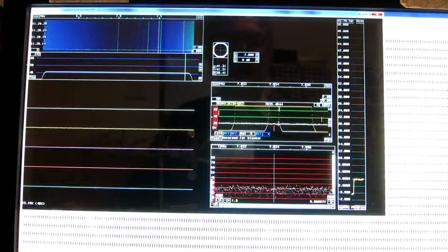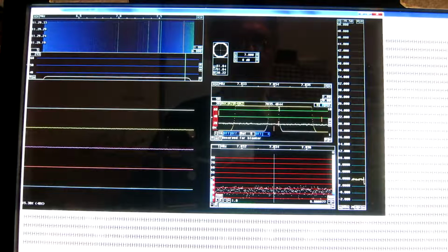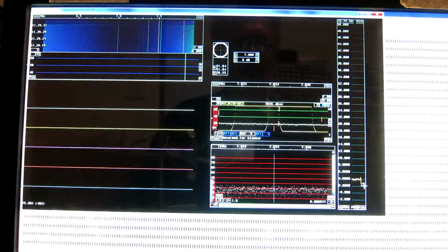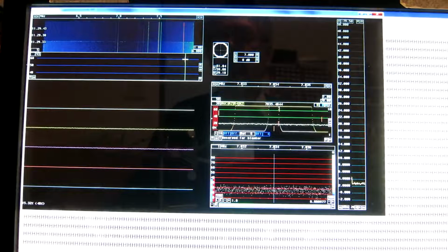Here, when I switch off the pulses, it is nearly 3 dB higher. And the reason is, of course, that the gain of the SDR-IP is lower, which Linrad compensates for, and the consequence is a degraded noise figure out here. The noise figure is nearly 3 dB worse.